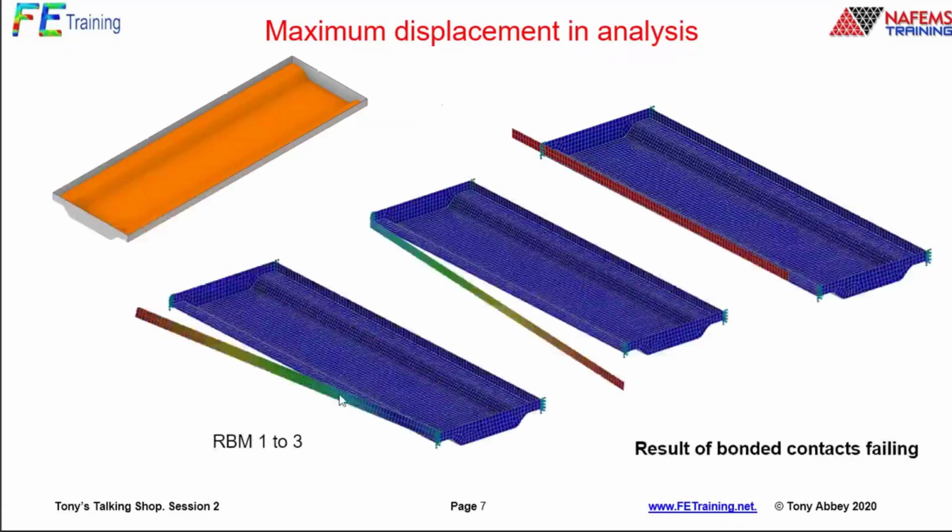So here's an example. This was a structure I ran, and I had issues with the CAD model. Basically, I had used a contact surface in this particular case to connect these different strips together. Due to the mid-surfacing and offsetting coming through from the solid geometry, it was easier, I thought, to just bond everything together. Now, I set the tolerances wrong in the bonding. So a couple of things happened.